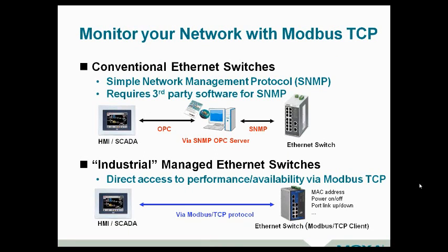And then lastly here, and we'll open up here to questions on this. As you're planning your network projects, don't forget about the Ethernet infrastructure as well. And I know one of the challenges we found is that oftentimes, customers such as yourself are thinking about the end devices and kind of forget about how to instrument the network architecture. And if you're using Ethernet switches, hopefully you're selecting managed switches, which give you ways to look at performance and availability of your networks. It's not easy to take a traditional Ethernet switch that only supports simple network management protocol and get that into your system.